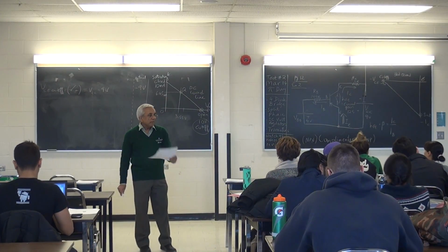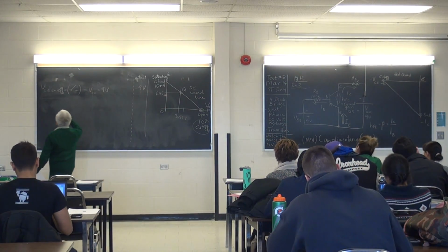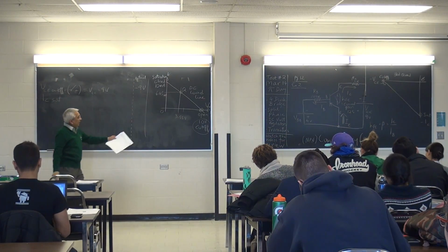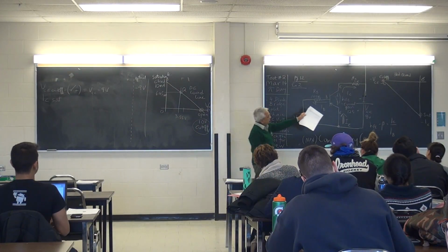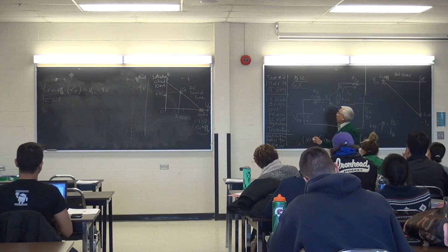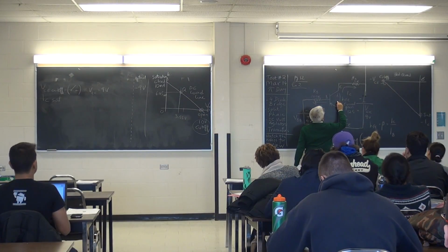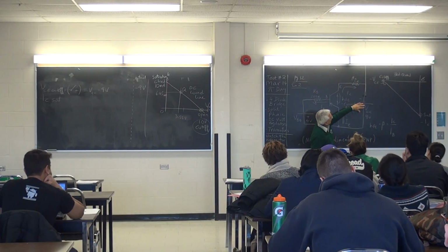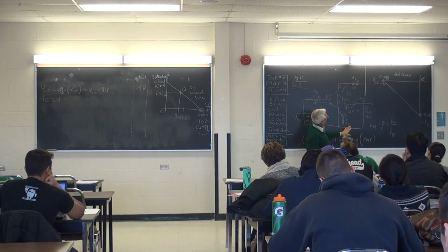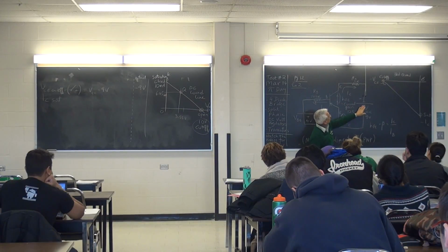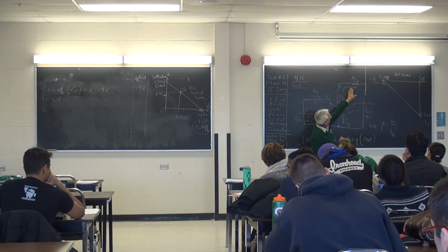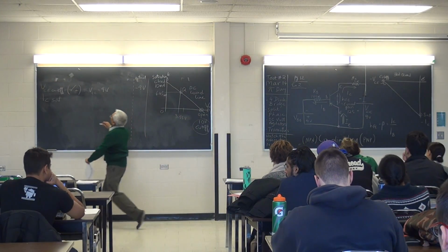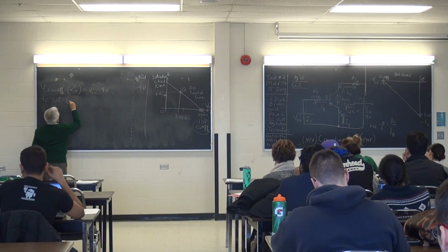Now, let's do the second calculation. IC saturation. That's the other extreme point, right here. That's when I replace this guy with a closed switch. If I was to replace the transistor with a closed switch, I've got a voltage and I've got a resistor. And it's a simple circuit made up of a voltage and a resistor. So what would be the current in this circuit? It would be V over R. So IC sat, let's show a symbol of a closed switch.